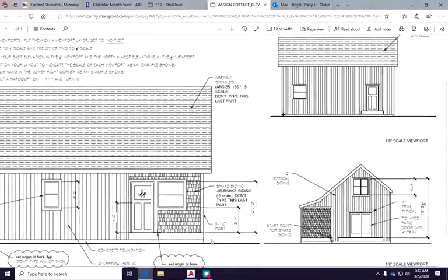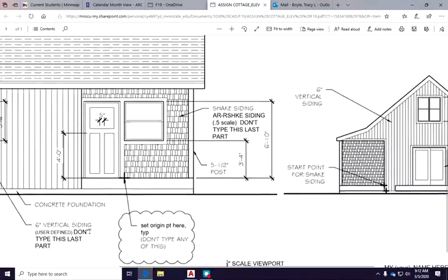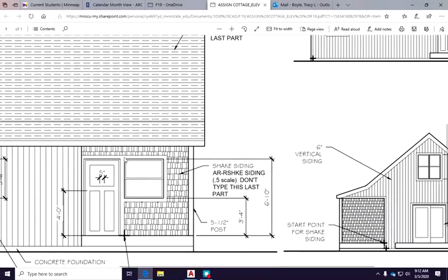And so if you look at a window, here's the trim. The darker line right here is the yellow line I just put in. We're going to offset it outward 4 inches to give ourselves some trim. And then when we get to drawing the window, we're going to go in 1.5 inches because that's the thickness of the frame.